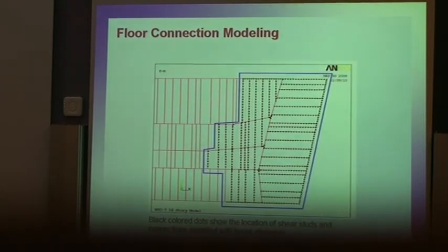That's just one example, but we did a lot of these for a variety of connections that were around the structure, and we ended up putting these models in the 16-story model, the ANSYS model, only on the right side of the building, because we knew that the initiating event would correspond to this region based on what we saw in that video. Just to give you an indication, this run took almost 6 months, because of the amount of iterations and convergence problems that you will see in these types of analyses. So it was very prohibitive for us to use this connection model all around the building. But we put it on the east side, as you can see here, for all the floors that were affected by fire.